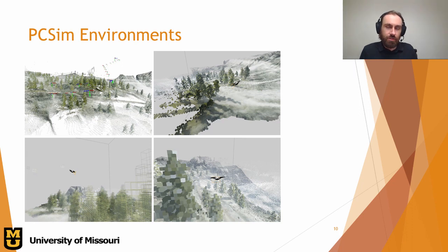If we do this multiple times as the drone moves, we can build up a dense reconstruction of the environment where every pixel in every frame becomes a point in the point cloud. Now, obviously this would lead to really huge point clouds if we saved everything, so one simple reduction is to just voxelize the environment and save one data point for each voxel, which is what we're showing here. Now we can do a lot with this kind of representation, such as figuring out where to go next or how to avoid running into obstacles. But in general, understanding how best to represent the agent's knowledge of the environment as a really high-level data structure is something we expect to continue looking at with future research.